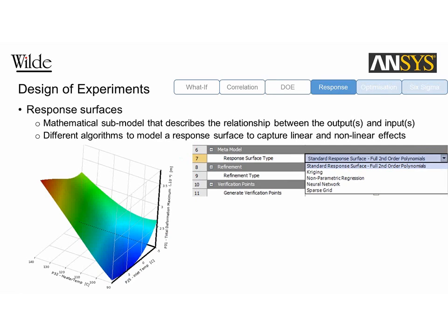Once you actually run the DOE, like I said, you obtain response surfaces, and these are nothing more than mathematical formulations that interpolate between the design points. Depending on your response surface, you might have a very simple quadratic or linear response surface, or you might have a very nonlinear exponential surface. And we've got several other models like Kriging, neural networks that can handle higher order response surfaces.